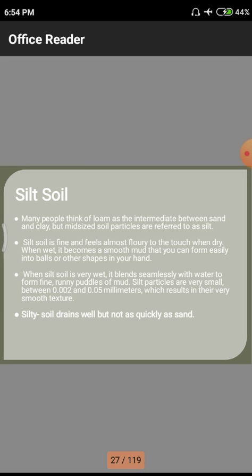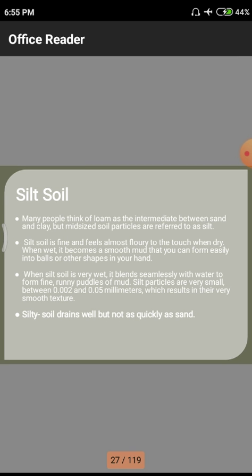Another one we have is the silty soils. In silty soils, the particle size ranges from 0.002 to 0.05 millimeters. Previously, we had 1 to 2 millimeters diameter for each particle, and the shape varies according to transportation and other site conditions. In silty soils, we have 0.002 to 0.05 millimeters, and we have some amount of bonding. That means when we mix 2 to 3 drops of water into a pinch of material, there will definitely be a bond formation.